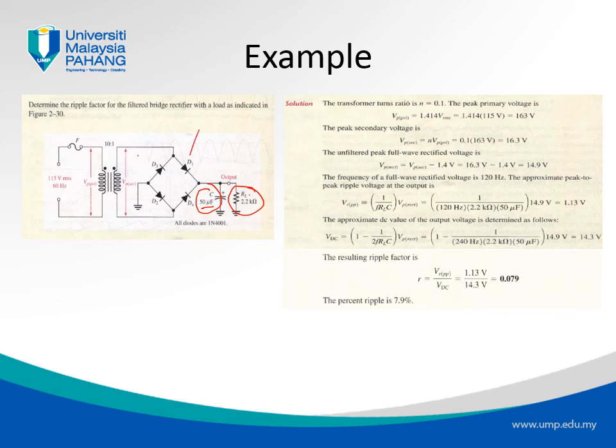And here we have a full wave rectifier, a bridge rectifier, right? Another thing that we also have to consider is the step down ratio of the transformer. Here we have 10:1. Okay, in order to start this, of course, we'll do it step by step. We'll look at the input first. And we know we have a primary transformer circuit and secondary transformer circuit. Of course, the first stage would be to find the V secondary, right?